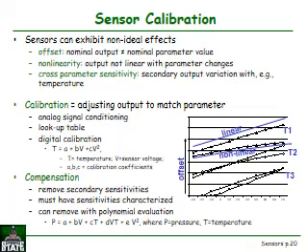This is sensor calibration. Calibration means that if the temperature to measure is 90 degrees centigrade, the sensor needs to measure a value of 90 degrees centigrade. If the sensor measures 88, there is some problem in the measuring instrument. So every certain time period you need to calibrate the sensor with standard instruments.